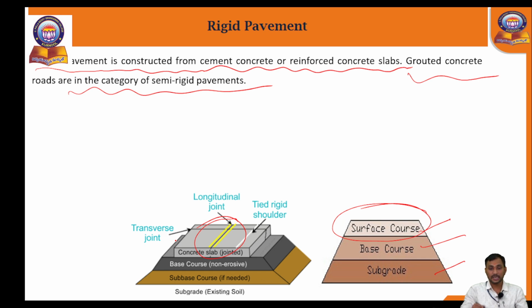My dear students, you can observe here the subgrade layer, which is nothing but topsoil. We have to remove the topsoil up to 120 mm to 150 mm of thickness. After that we add 40 mm size aggregates with some soil for bonding purposes. Slowly after that, sprinkle the water and compact it with bulldozer vehicles. This process is the same for flexible and rigid pavement.